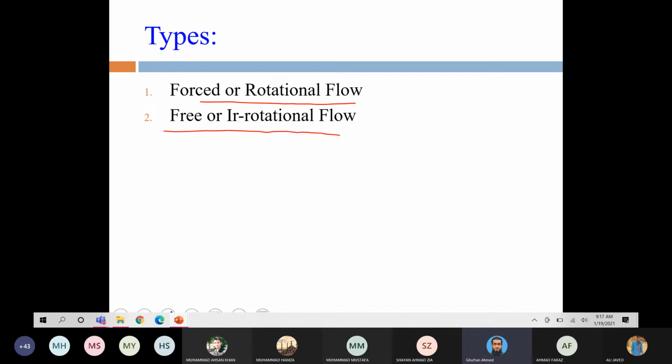But as you remove the blockage, the water will start flowing in the basin, and at the very last moment it starts spinning around the wash basin and creates vortices. So that is an example of free vortex: you are not applying a force, but due to the curvature or the shape, the water spins. So that is the free vortex.